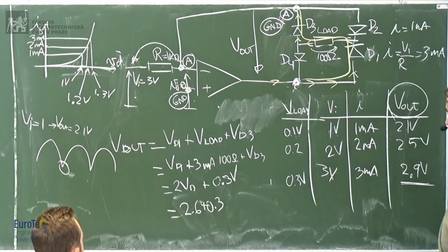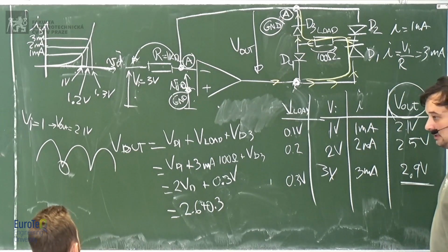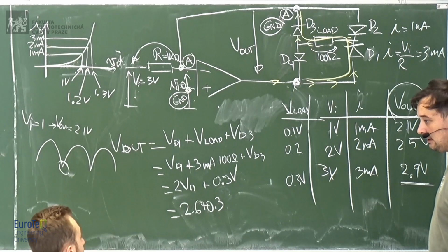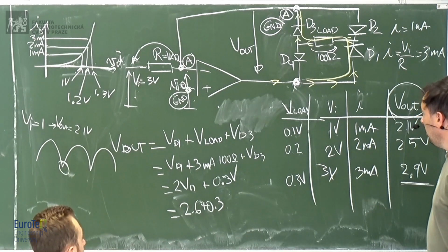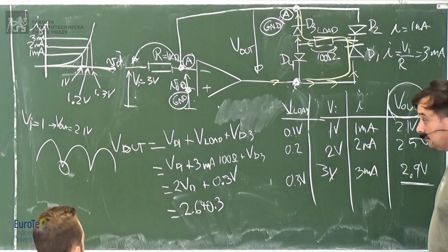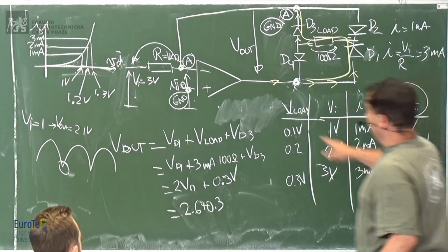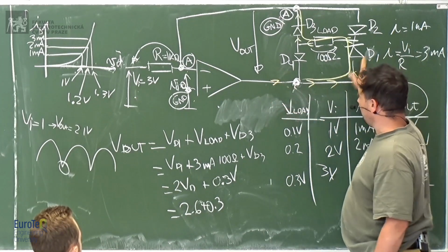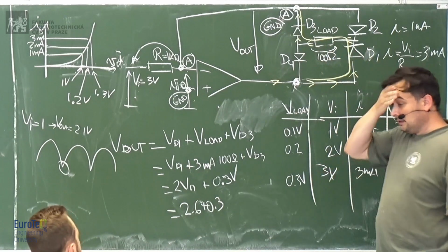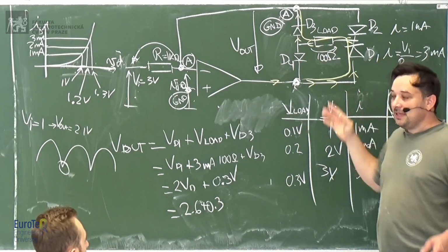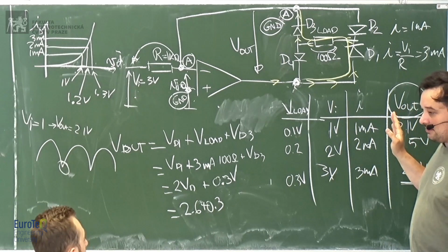And this is how you can use an operational amplifier to basically do whatever you want. But now the current to that load will be limited by the op-amp. Yes, in this case, the current is generated by this operational amplifier. But I'm guessing you could use some transistor. We did this earlier. It's used typically for signals, okay?